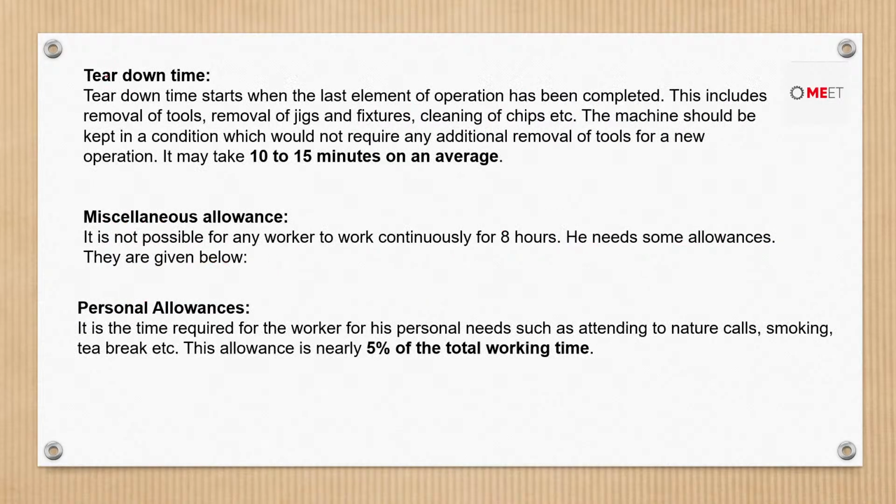Next, we have tear down time. Tear down time is when the last element of the operation has been completed. It includes removal of tools, removal of jigs and fixtures, and cleaning up of chips. Basically, it involves the cleaning of apparatus so that when the next operator comes to start, the machine should be in a ready-to-start condition.